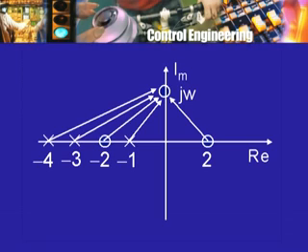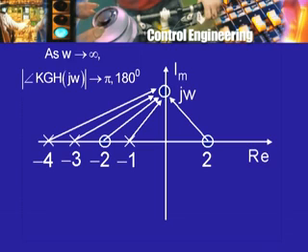So, as the frequency goes down or as we approach the DC end, the phase shift will be almost 180 degrees or pi radians. Of course, will it be a little more than 180 degrees or a little less than 180 degrees? We cannot immediately say. One will have to do a little bit of calculation or estimation to find out what is going to happen, but the limit is going to be this. At that end, the gain was not infinite, the gain was not 0, the gain was some finite number. So, the gain is finite and the phase shift was 180 degrees at the DC end. What about the high frequency end? At the high frequency end, all these vectors will make angles which are nearly equal to pi by 2 each.